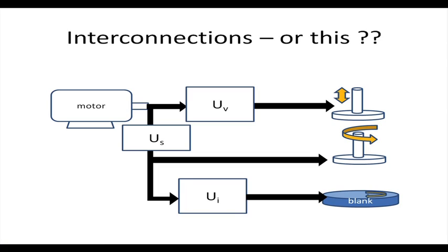So, if I change speed, the number of strokes per minute are changed, but the feed, unfortunately, is getting affected. Fortunately, the number of teeth being cut is not going to get affected, because the position of UV is such that it is not affecting the RPM ratio. As you can see, bifurcation has taken place from the very beginning. Okay. So, here the problem is that feed gets affected.